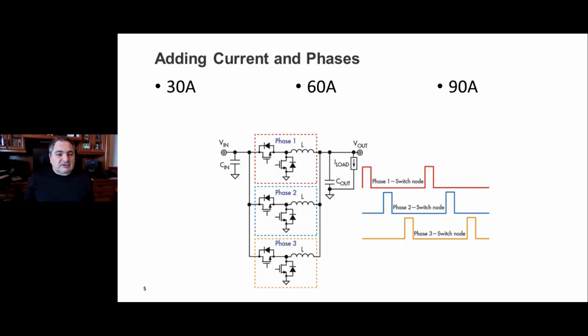So I rounded this up and added some margin. Let's say there's 270 amps peak. We're going to design a PDM for 270 amps continuous or peak. So we divide 270 by 30 amps and we get 9 phases.